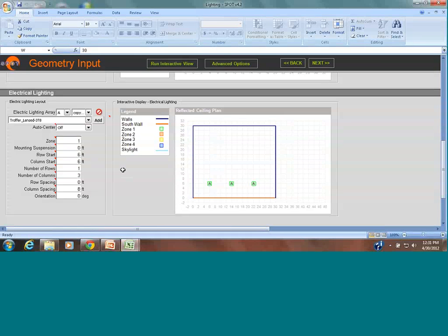Okay, so that's during your early architectural analysis, seeing how big of a window you need and such. Using a spot generic light fixture makes a lot of sense because that will help you go through the different iterations a lot easier. Once you have the geometry figured out and make sure all your daylighting solutions work, you're bringing light all the way back to the classroom, and you're protecting from glare and discomfort glare, and let's assume that you've done all of that, then it's time to put in the actual light fixture that you're planning to use.